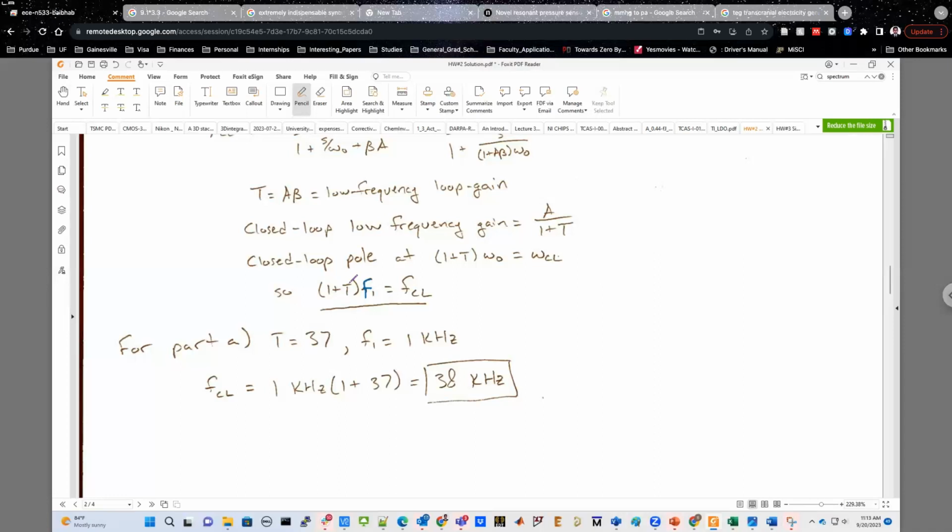So what is the gain bandwidth product? At this point, the product of your gain and frequency is 100 times, let's say, F1. At the next point, it's 10 times 10 F1, right? Because your frequency became 10 F1 and your gain was 10. So what's the gain bandwidth product? It's still 100 F1. At this point, your frequency is 100 times more, but your gain is 100 times less. That is still 100 times F1. So the gain bandwidth product remains the same at all points in this particular plot.